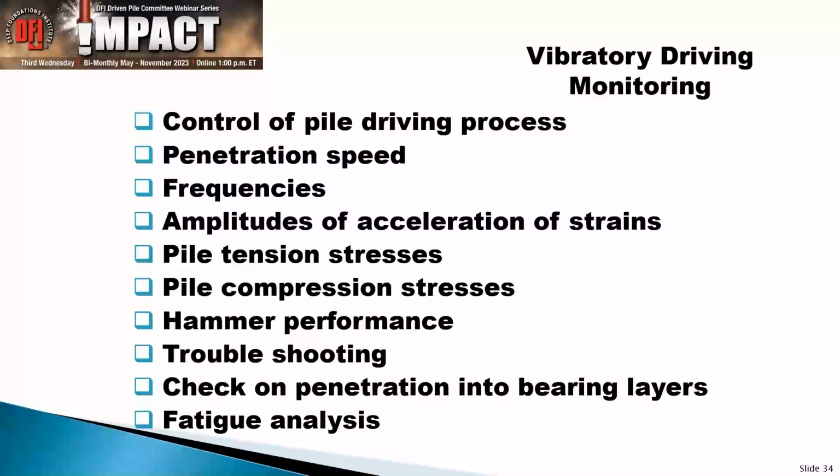That scares structural engineers, because they're saying, oh, with fatigue, you cannot do that. Now, the nice thing is, since the stress levels with vibratory driving are a lot lower than with impact driving, in the end, it's really not a major issue. Most of the time, the fatigue aspect of pile driving with the vibratory hammer is even less severe than with an impact hammer, but it's something that you need to look at, and most of the time, people don't think about it when they're using it with an impact hammer, but with a vibratory hammer, it's often asked for, and you need to look at this whole thing. And then hammer performance and troubleshooting. Yeah, exactly the same thing.